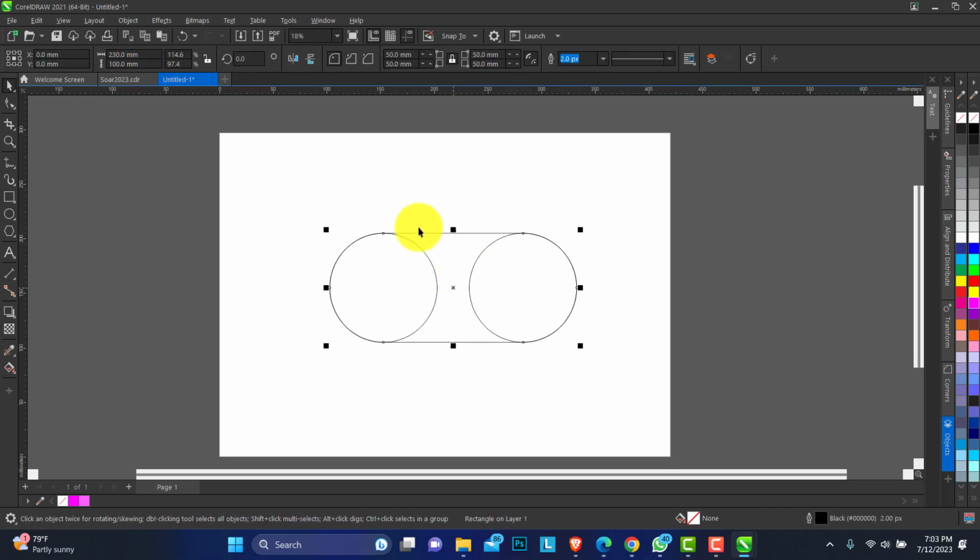So now we're going to rotate this rectangle, but we have to change the center. You click on the center of the rectangle, it changes to the rotate gear. So you change the center of the rectangle to that of the circle. You click and drag this where you are moving it. Note that it will indicate to you to snap to the center. You leave it there and move this gear, click and drag, holding down your Control.